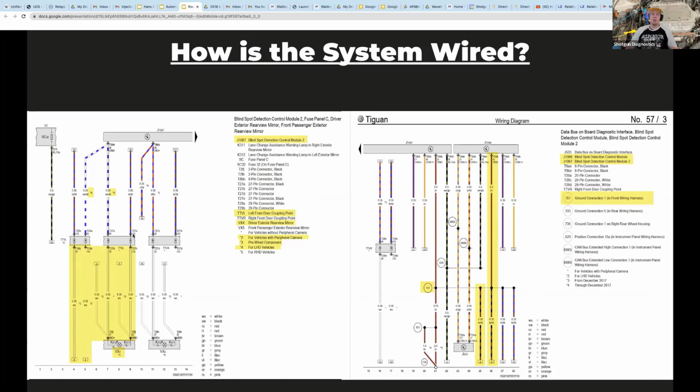And he said, okay. This guy was actually very sharp, much sharper than a lot of the mechanical shops I talked to. And he understood exactly what I was talking about when I said run a bypass harness and see if it fixes it. He ran the jumper harness and it did actually fix the vehicle. So he did not have to replace the module. He repaired the wiring and he did calibrate it and it was fine.